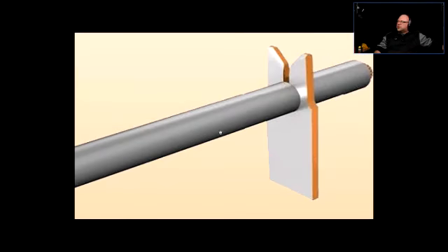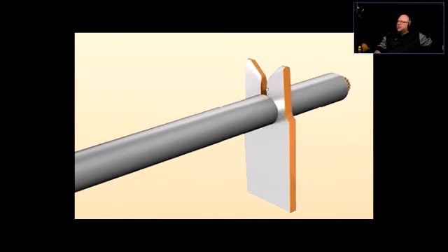When you are pushing the conductor in, and this connector bites into the insulation and makes the contact, there's a chance that it could break some of the strands. Actually, there's a huge chance that it's going to break some of the strands.